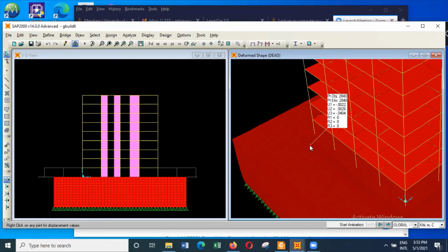The displacement of the soil here is about 40 millimeters. Now that is the deformation of the soil. And as you come this way, the deformation of the soil has reduced to 35. And when you are coming this side, it is 35 and so on. And if you look at the vertical deformation of the structure, 46 millimeters.